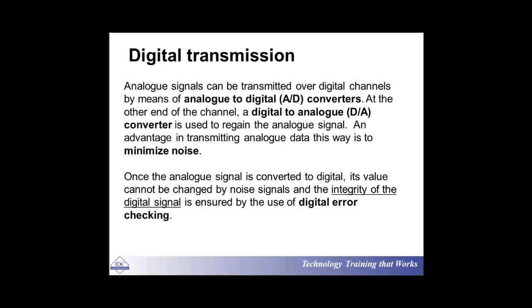If you have overload, or monitoring over the pressure and the level of the SF6 gas, or control over, let's say, the temperature of the windings of a transformer, all this information at the beginning is analog. So you receive this information, you digitize it, and now you make this transmission and reception in terms of digital signals, which is much easier, much better, and you gain a lot higher quality.